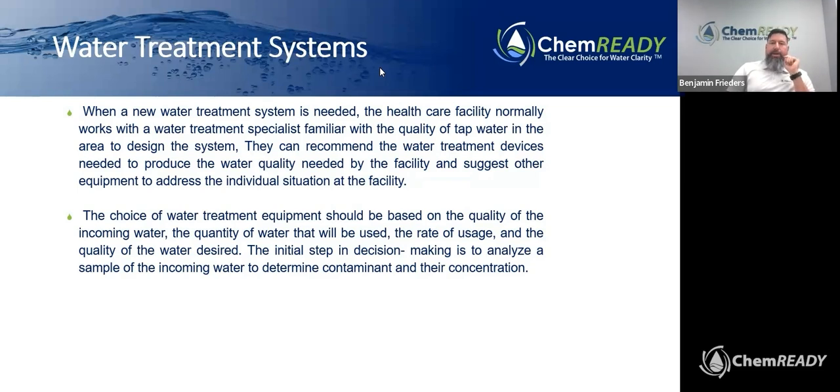So for example, GetChemREADY is based here in Twinsburg, Ohio. I live in Indianapolis, Indiana. The differences between water quality from the city between the Cleveland area itself and the Indianapolis area are vastly different. So if you're in Cleveland, you don't have to do a lot of treatment to get within the standards of utility water. Whereas if you're in Indiana, then you need to have some type of treatment to meet those utility water specs. So someone that is familiar with the area that your facility is located is vitally important in terms of the decision to become compliant in terms of water quality treatment equipment.